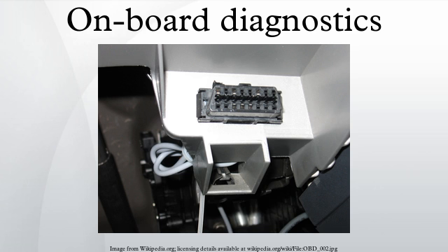Each manufacturer used their own diagnostic link connector, DLC location, DTC definitions, and procedure to read the DTCs from the vehicle. DTCs from OBDI cars are often read through the blinking patterns of the check engine light or service engine soon light. By connecting certain pins of the diagnostic connector, the check engine light will blink out a 2-digit number that corresponds to a specific error condition. The DTCs of some OBDI cars are interpreted in different ways, however.